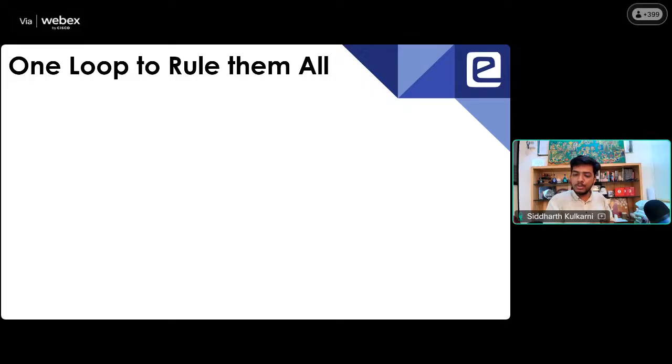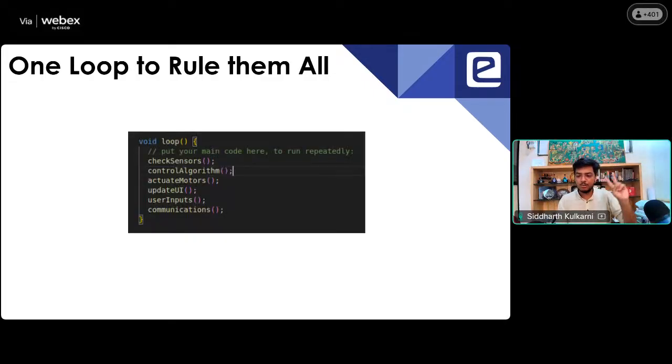So how would you do that in a traditional Arduino-like fashion? So I'm assuming everyone is familiar with Arduino. Still, we'll recap a bit. So what Arduino does is Arduino has these two functions. One is called void setup and another is void loop. So things that you want to be executed only once every time your system is powered on, you put in void setup. While the things that you want to be executed repeatedly in a cyclic manner are things that you put in the loop. So for example, starting up, initializing the screen, initializing the sensor, setting up all the parameters, etc.